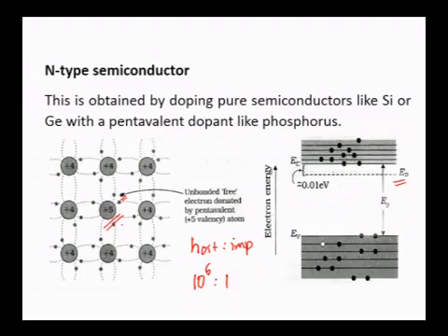So students, remember, in N-type semiconductor, free electrons are majority charge carriers. So we can say that Ne is greater than Nh. Whereas in case of intrinsic semiconductor, the number of free electrons will be equal to the number of holes. But in this particular case, the number of electrons will be more. Therefore, electrons or free electrons are called majority charge carriers.